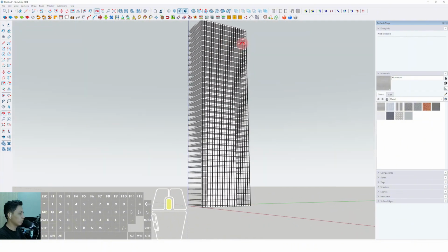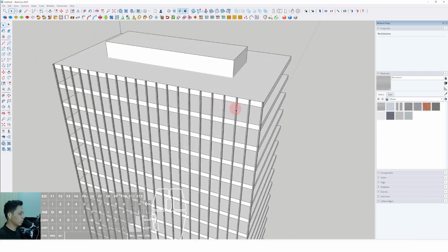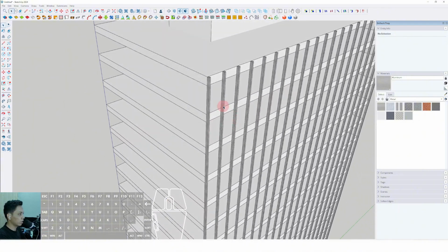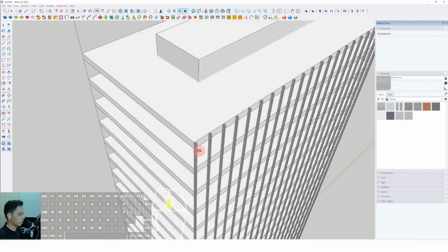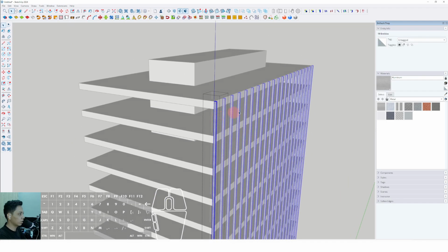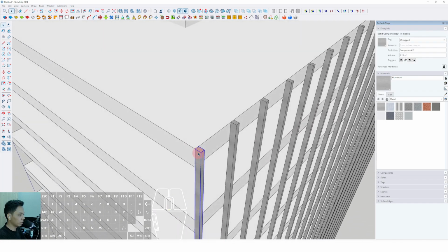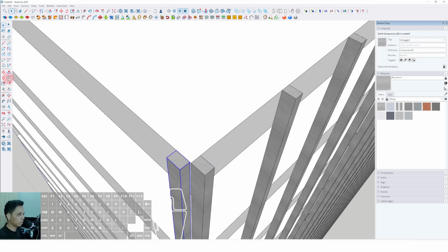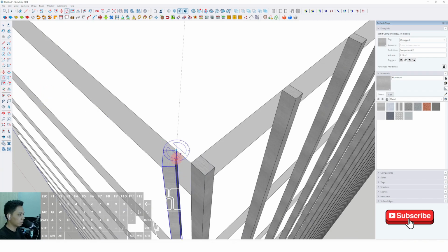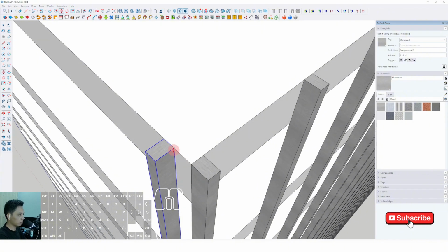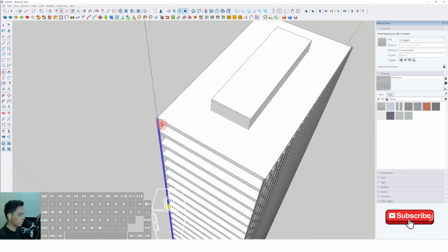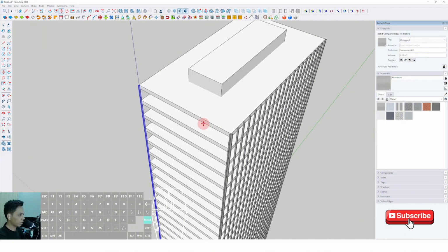So if you feel the distance is too long, you may make it smaller than this. Okay, well, now we can duplicate this one to the other side. We can select the move tool, press Ctrl, then we rotate it, then we can type 90 degrees and select move, place to this position, then we select move, press Ctrl, click from this point until this point, then we type 10 slash enter.